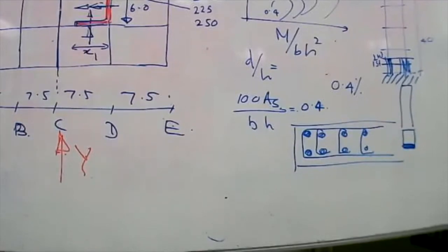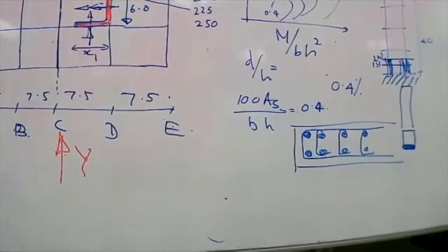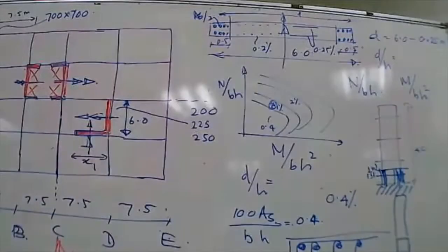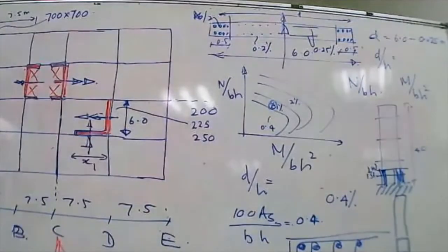Any other question? Yes, one more question. So here you are assuming that the geometric center and the stiffness center are the same. Basically, no, I'm not assuming. I have selected the walls in such a way that it becomes that way. But due to the architectural arrangement, if we can't make it coincide, is it okay? Is it recommended to design with the twisting mode?